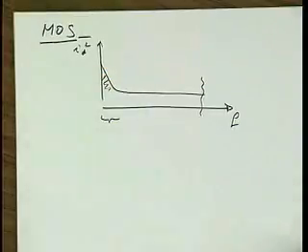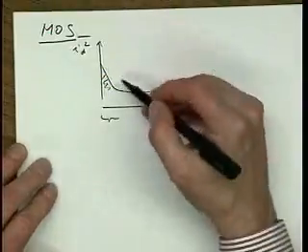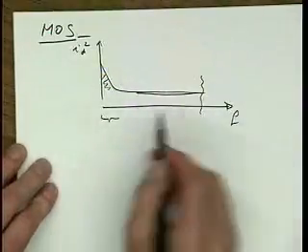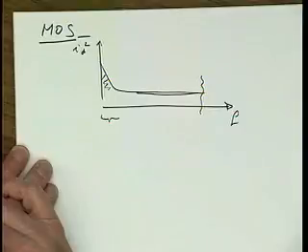But one sort of vehicle or one figure of merit, if you want, that is helpful in determining whether flicker noise might be a problem in a particular application is the so-called 1/f noise corner. And at higher frequency, of course, thermal noise dominates, right?